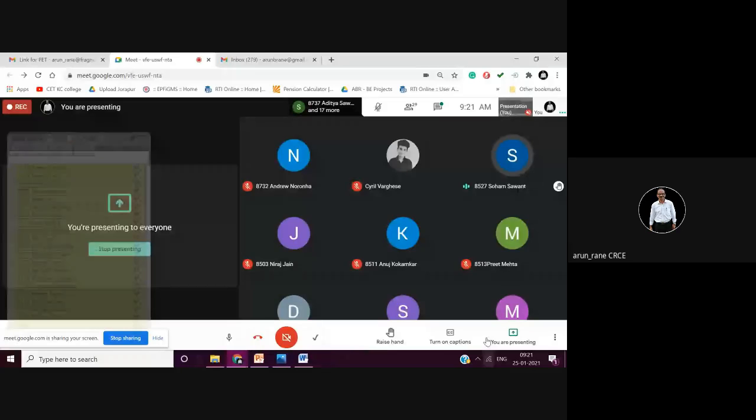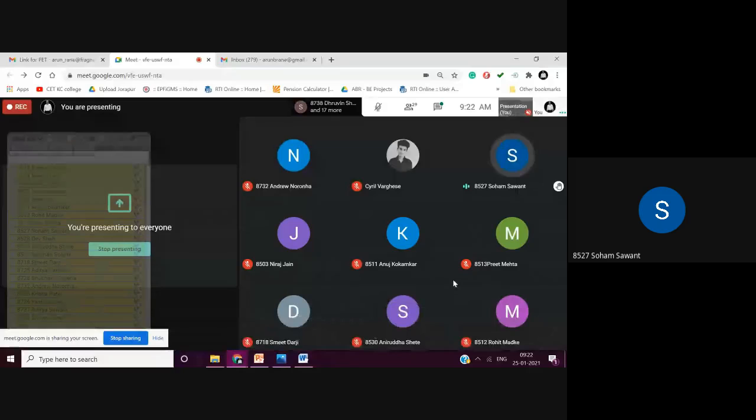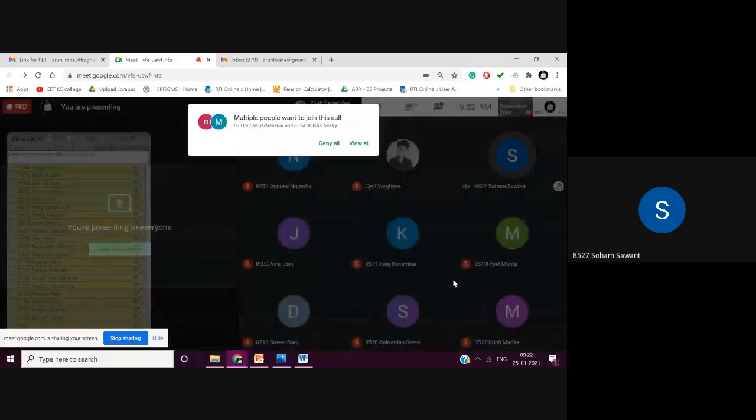No, here the quantity is 10,000 pieces. And that's what I'm saying. If there are 10,000 pieces, why can't we? Because if the threaded area is small, why should I take the whole batch to the thread rolling machine? Because again, it will include transportation time as well as a bit of cost for using a secondary machine. That is what I'm telling now.